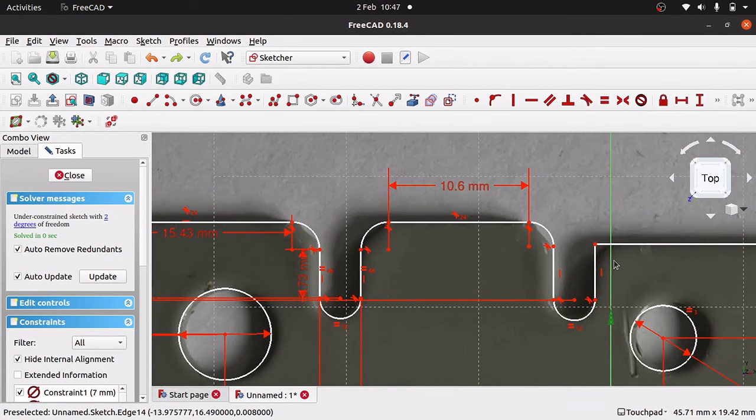So now we can actually move over to this one and do the same. So I want to fillet that off. Go to our fillet tool. We're just going to fillet this off here, so looking for where that starts and ends. Now because the fillets are on different lines, so this fillet is higher than this one, we need to do some additional constraining in here.